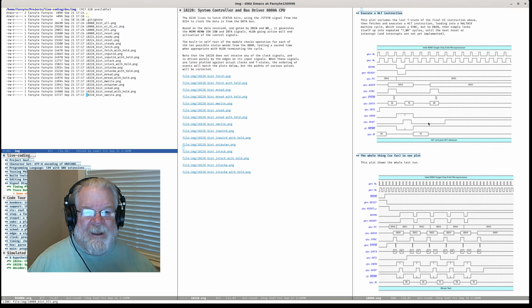That's why. So we get an 8A, which is halt acknowledge, and the CPU then dives into what's called a halt machine cycle. So during T1, we assert sync. During T2, we release sync. And then we go into TW. It's actually a specially named state. Halt wait, I think HW. And we wait in HW until we either get a reset or an interrupt. So at this point, I could issue a reset to the microprocessor and see it come out of reset again, maybe give it a different set of instructions, or I could issue an interrupt, which we have not implemented yet.